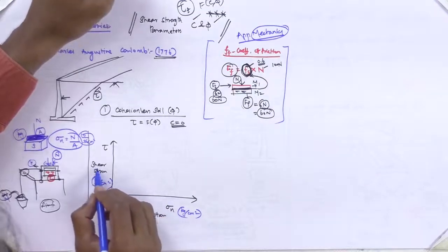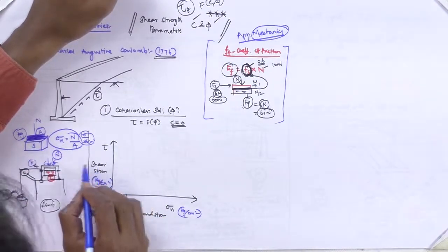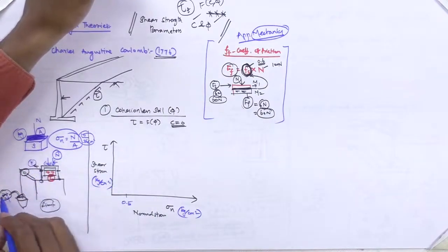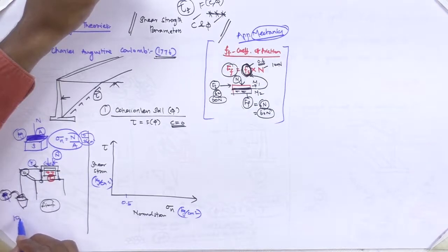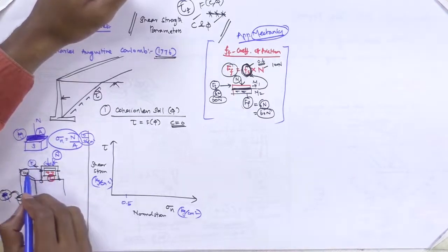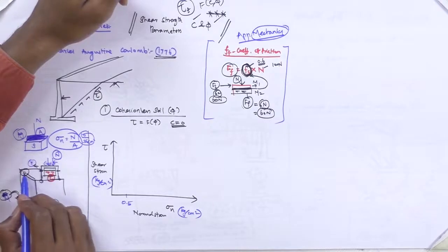So the shear stress is going to be developed. So he keeps on adding the soil material measured. So at 10 kg, or let us consider 12 kg he has added, and the soil has failed, which means the movement occurred.